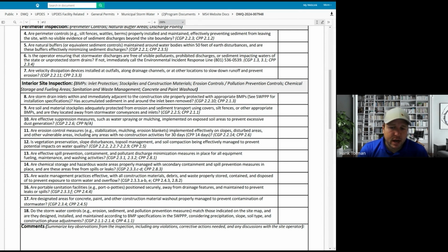Next, our waste management practices. Remember, the dumpsters and the portable toilets are part of the SWPPP. We have to make sure that the dumpsters are being managed properly, mainly so that blowable trash doesn't come out. And the portable toilets, as always, are a huge risk of very dangerous pollutants, right? Including sanitary wastes and also the chemicals that are used inside of portable toilets.